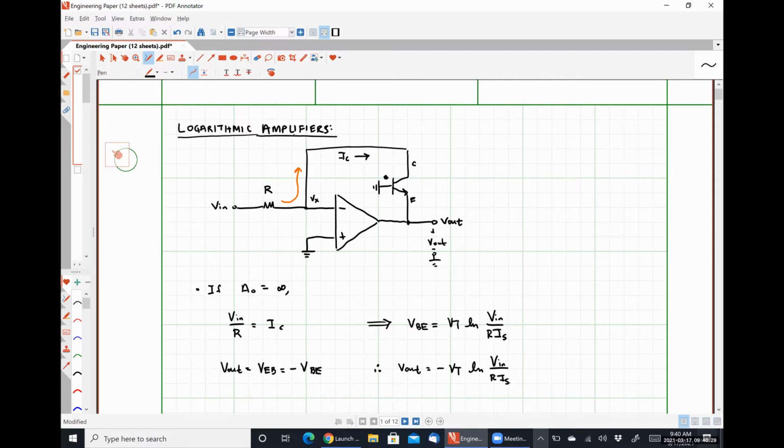Output voltage was always at the positive power supply or the negative power supply, right? So effectively all of that near infinite open loop gain gets applied to whatever signal you have at the input. In this case, a negative input signal would cause our output to swing to the positive supply rail. So our output would go towards VCC plus.